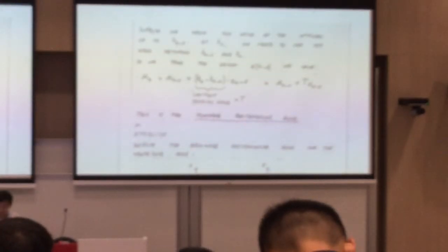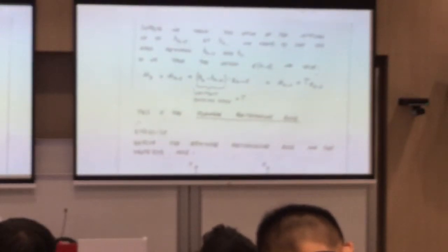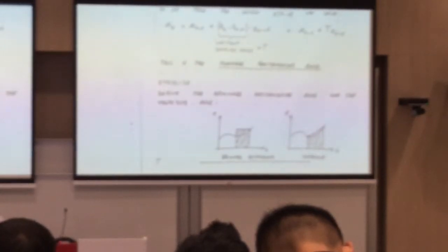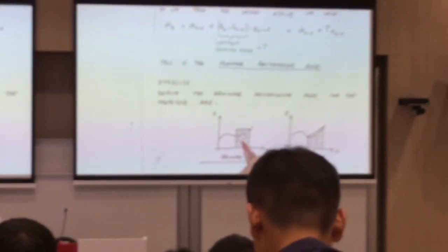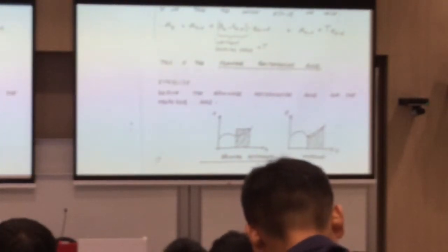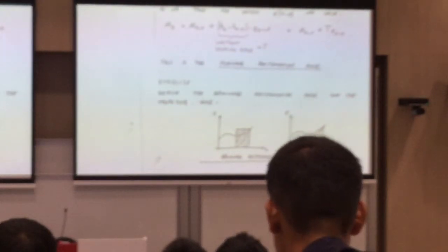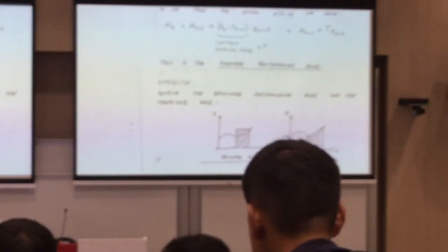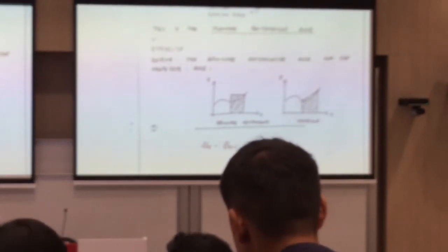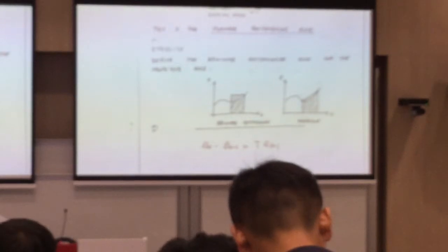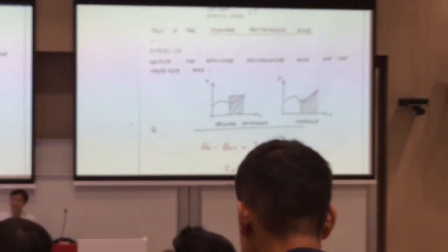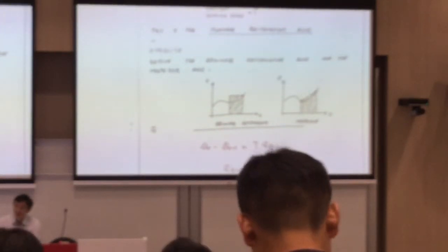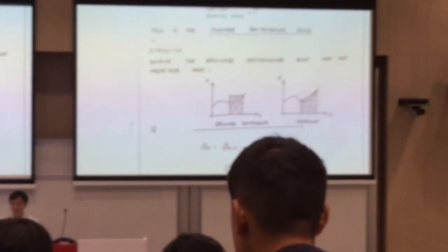And now if you notice, this one is also represented by the difference equation here. Right? Because the difference between your u(k) and your u(k minus 1) will become the value. So you see, if I present this one, it is your integration, right? If I present this one, what is it? This one is your differentiation. And this one is your backward differentiation. Right?